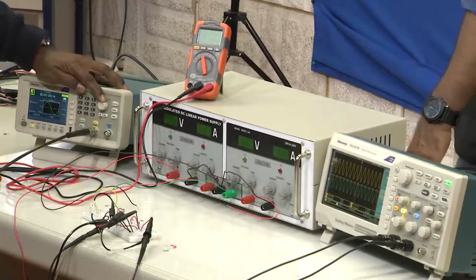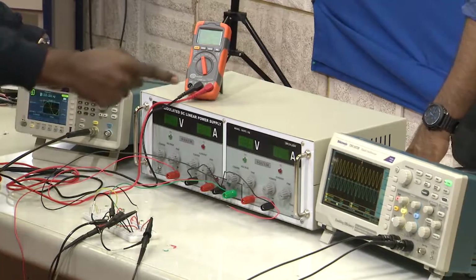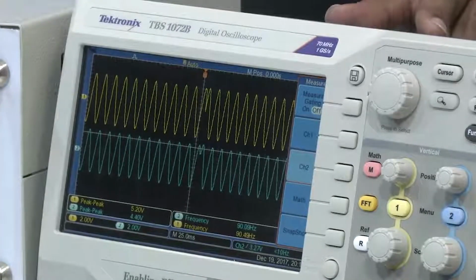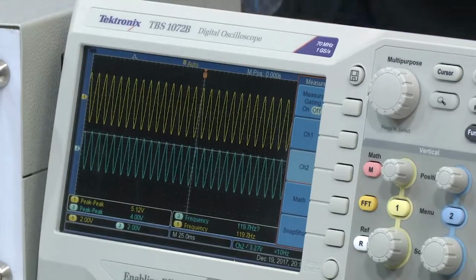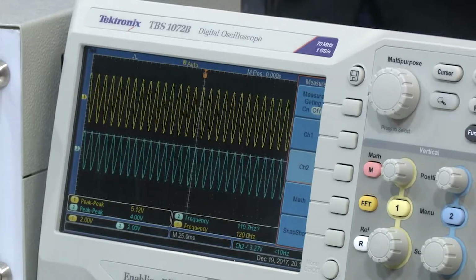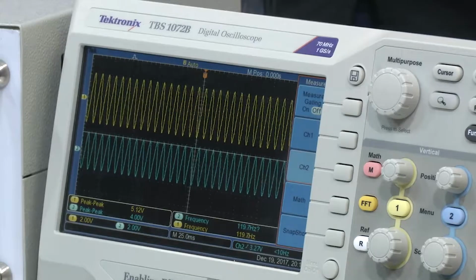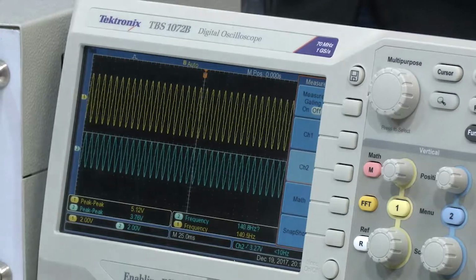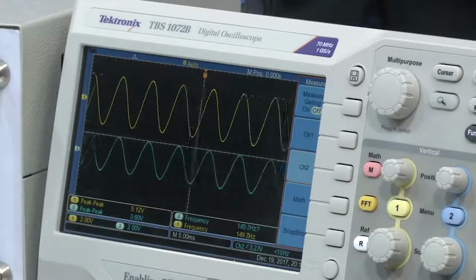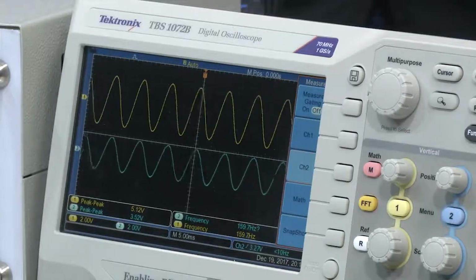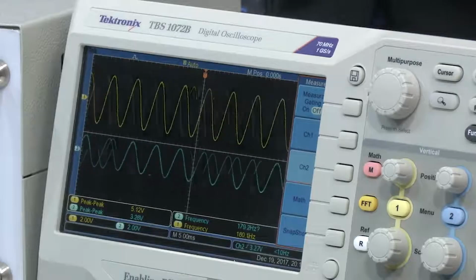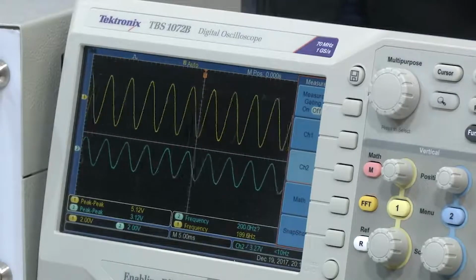Okay. So, we are increasing the frequency to 60 hertz. You can just look at the oscilloscope, he is increasing to 60 hertz, 90 hertz. So slowly, 100 hertz, still you can see it is following, 119, 120, still following 120, and now 150, and suddenly you see that the amplitude is getting clipped, or decreasing.